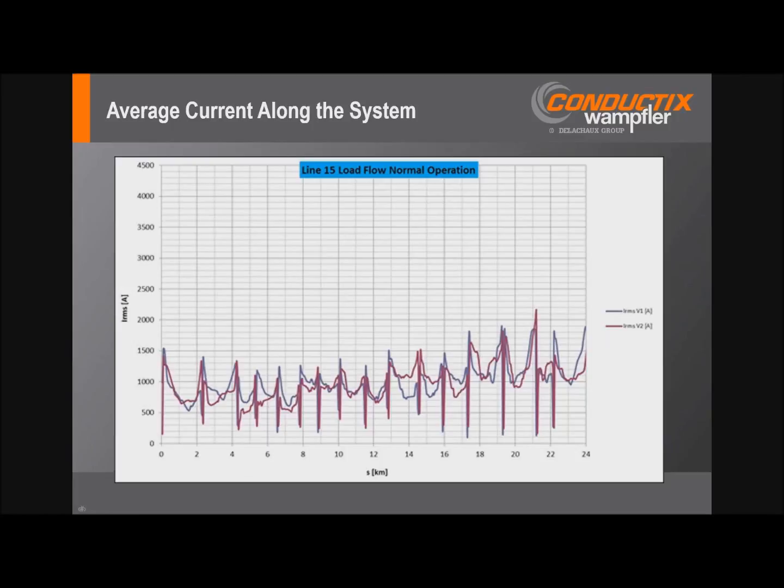Check expansion gaps at various times to make sure that those are moving, if they were set properly initially, so that you won't run out of stroke of those. Look at the areas where the collectors are making and breaking contact with the power rail to look for electrical erosion. And then again, look at the condition of the collector shoes. Sometimes those will tell you, based on nicking or chipping of the leading edges, that there may be some impact going on out on the system.